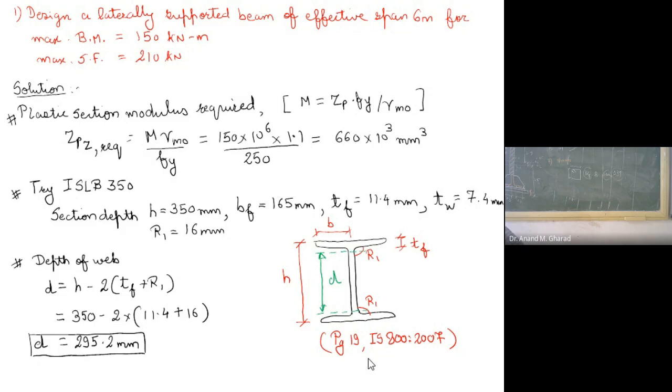तो देखो, "laterally supported" लिखा है। तो मैंने जैसे आप लोगों को एक्सप्लेन किया कि most of the multi-storied buildings, which are made up of structural steel, उसमें मेटल डेकिंग या फ्लोर डेकिंग जिसको हम कहते हैं, वो प्रोसेस फॉलो होती है। इसका मतलब this beam may be embedded in the concrete, rather the top flange of this beam may be embedded in the concrete, ये हम assume कर सकते हैं, and that assumption is very correct. Assume भी करना है ना, कुछ दिया तो है नहीं, ठीक।